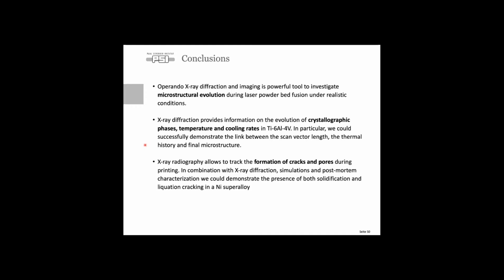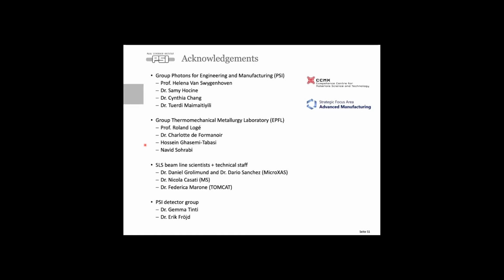Using radiography, we can see the formation of cracks and pores during printing. And for our nickel superalloy, in this way, we could combine it with diffraction and simulations and also post-mortem characterization. We could show the two different cracking mechanisms present in these alloys. With this, I will show the acknowledgements again of everybody who collaborated on this work and also the funding agencies. I'm happy to answer any questions you may have.